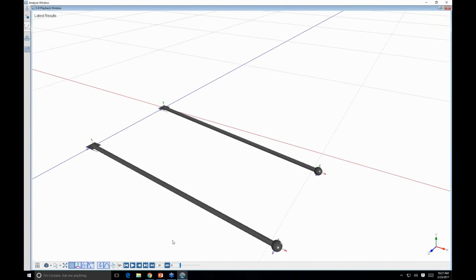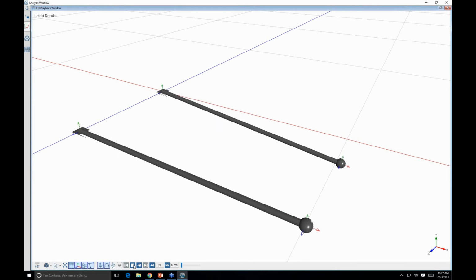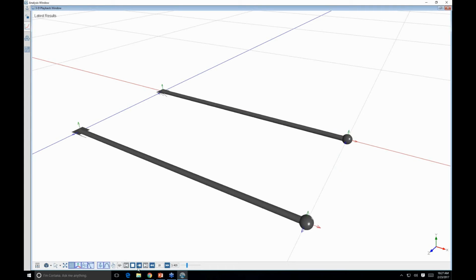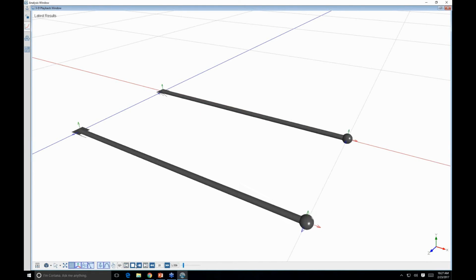As I told you before, this system is the old system, the one that we tuned using the parameter sweep, and the second system is the one where we tuned the PID control with the tool embedded inside the PID tuning template. So if we press on play, we can see that these two systems have different performances, especially the one tuned with the dedicated template goes to the horizontal position much quicker.